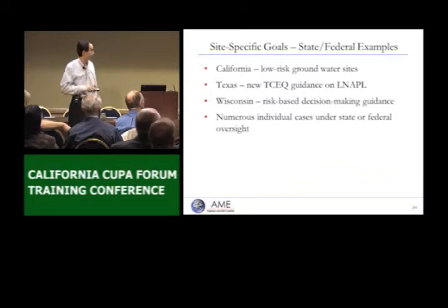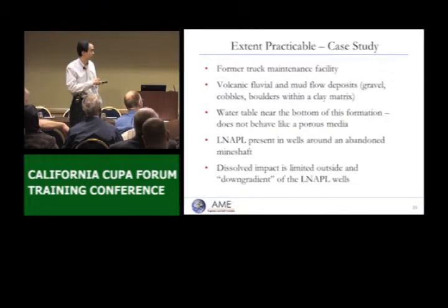So, well, this is a look at it in cross-section. These wells are screened in a deeper aquifer. So basically, these wells are screened in our formation of concern. These blue tubes represent the historical range of the LNAPL. So it's as high as this, and this is likely a purge condition. It goes out, instead it goes in this direction, which follows the apparent hydraulic gradient. It can also go back.